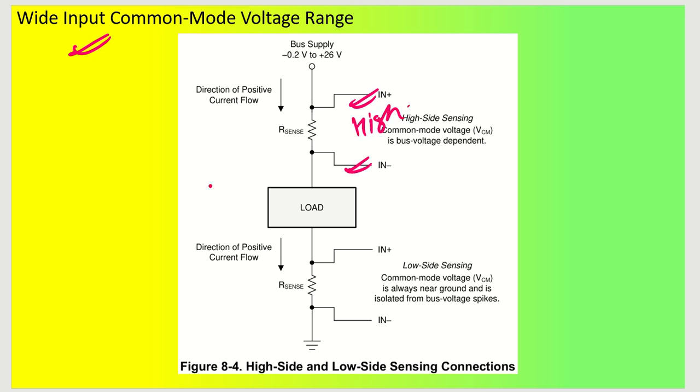Okay, so in high side, this is my supply voltage. So let us say we have a 12 volt application, so 12 volt input will be there. Then put your R sense that we will be calculating later on in our design.